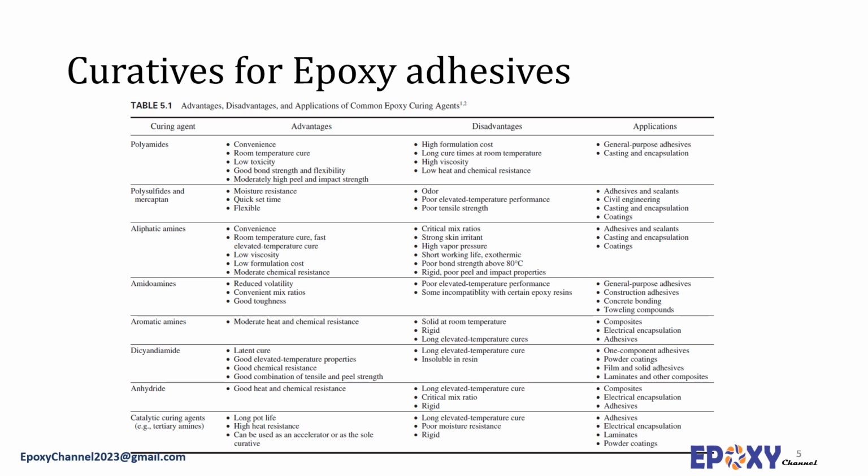However, common epoxy adhesive systems are formulated based on diglycidyl ether bisphenol A resins, DICY curing agents, and toughening agents, for example CTBN, and they show Tg values of around 100 centigrade.